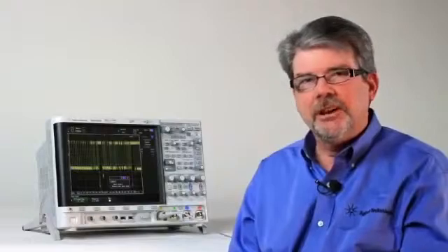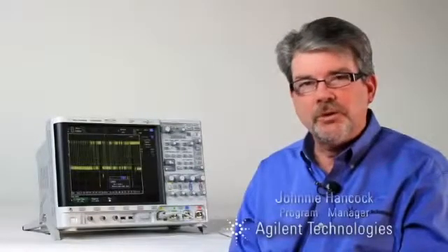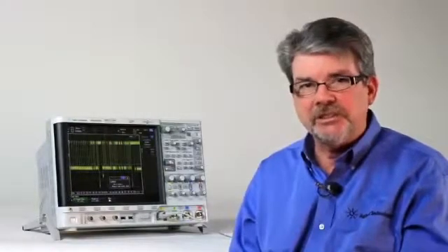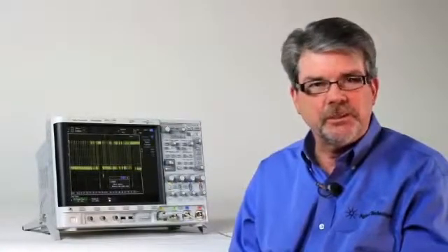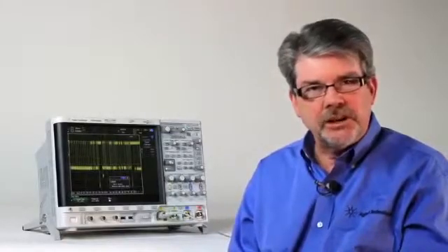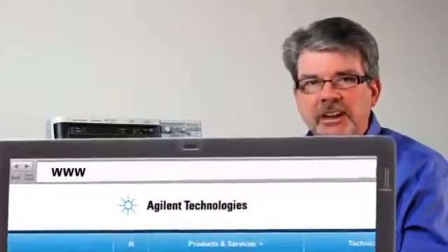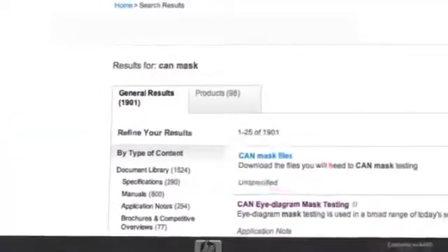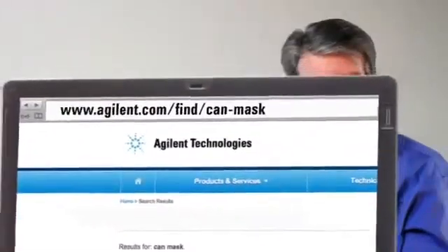In this short video, I will show you how to set up the Agilent InfiniVision 3000 and 4000 X-Series oscilloscope to perform eye diagram mask testing on a differential CAN serial bus signal. The first step is to download the various CAN mask files that Agilent provides on our website. These mask files are available at no charge.